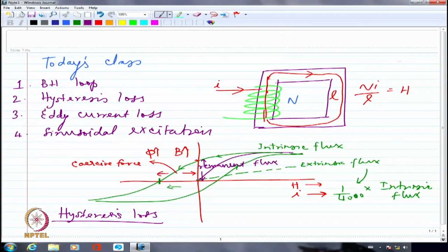So that is really not going towards any productive or useful work, but it is establishing the magnetism in one direction and the reverse repeatedly. That's all it is doing. This is unavoidable, as long as we use a ferromagnetic material, because it has this inherent property of flux lagging behind the current. So this hysteresis property gives rise to a loss called hysteresis loss.